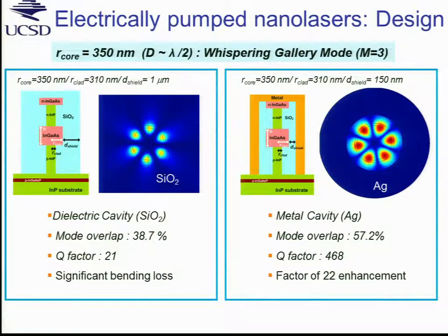So it was P and N indium phosphide contacts to the indium gallium arsenide gain media. To get the cutoff, now it's tricky because it's a high index dielectric. To get a reduced effective index, we need to undercut the indium phosphide such that there is no propagation of the mode in this direction. So that's what happens. And if we don't cover with metal, this is the plot of the simulation showing that the mode is really sitting quite a bit in the air, in the low index dielectric in this case.